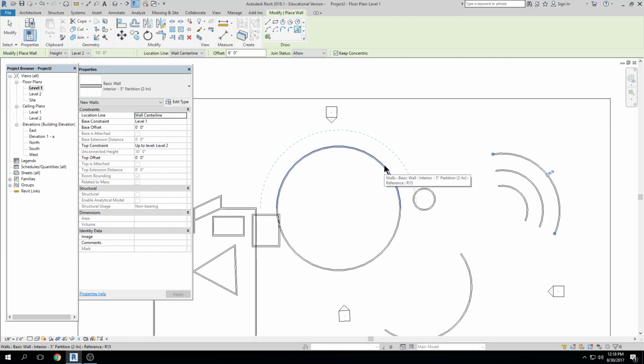Revit took me a little while to get used to drafting in. When you've only drafted in Revit, that's great, but when you've drafted in both Revit and AutoCAD, it takes a little getting used to. In AutoCAD, the way you go about it is you draw a lot of extra geometry: you're offsetting things and then deleting the offsets you don't need, drawing midlines to mirror across and then deleting those mirror lines, and drawing past items and then trimming off what you don't need.